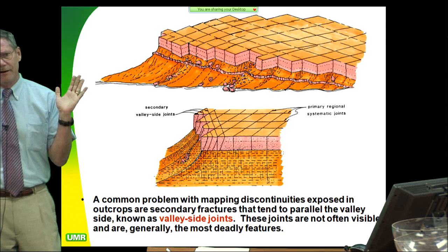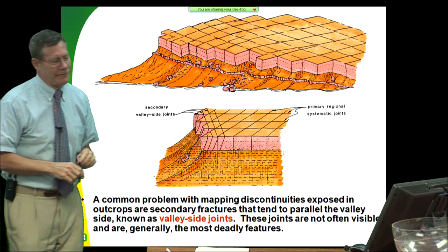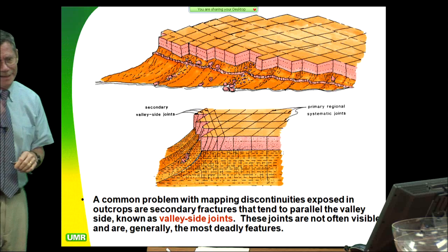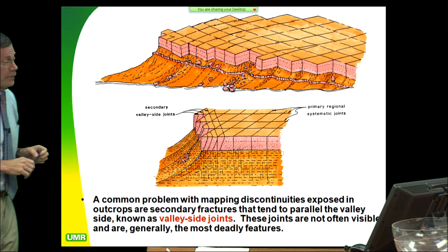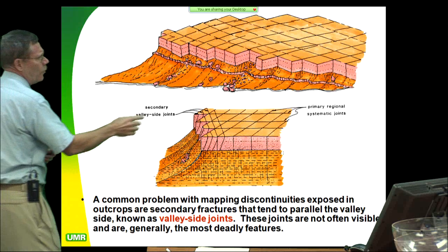Valley-side joints are always dangerous because nobody sees them during construction. Glen Canyon is another one. They didn't have a failure, but they spent 7 years and 4,000 rock bolts trying to hold these things down and keep the water from going through them.